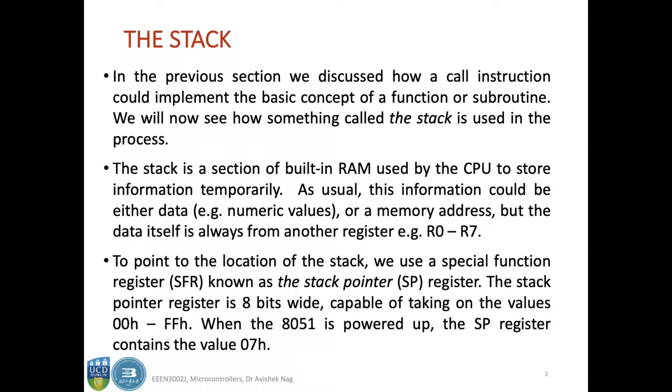So the stack is a section of the built-in RAM. If you recall, we had the built-in RAM, and then we had several special function registers within that built-in RAM. So stack is one of them, and it is used by the CPU to store information temporarily.